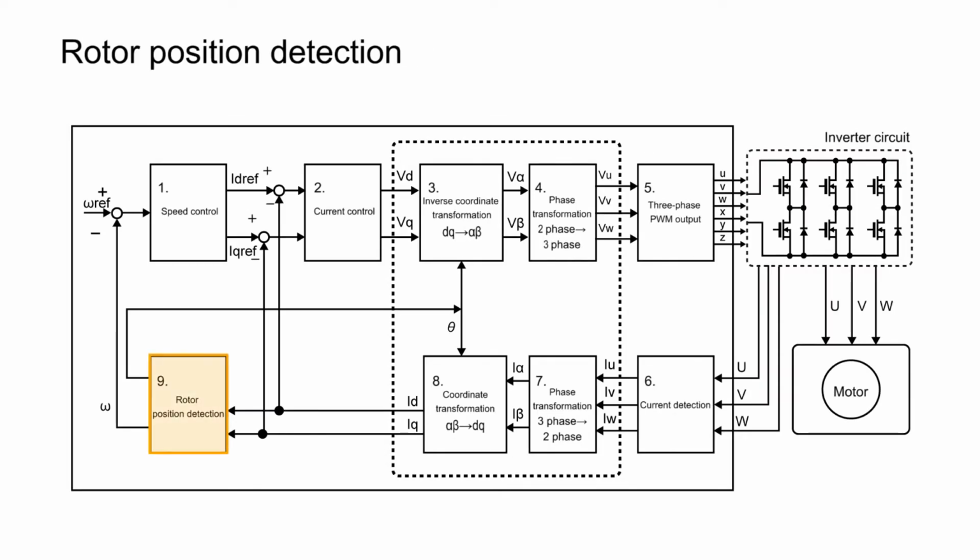We describe position detection. In sensorless control, a rotor position is estimated using the amounts of current of the magnetic field component, ID, and the torque component, IQ. And the speed, omega, and the rotor angle, theta, are calculated. Back EMF voltage is used in calculation to determine whether the obtained speed, omega, and rotor angle, theta, have reached the estimated values.